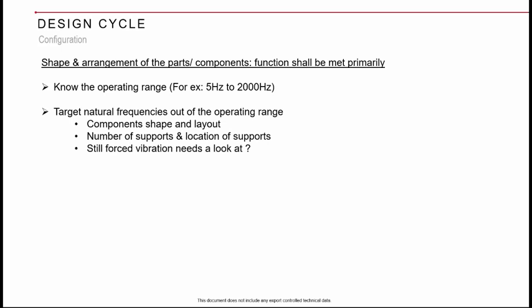See, I have kept my natural frequency away from the operating range, so I don't have any resonance condition now. But still, is it required to consider forced vibration? Yeah, I think yes, sir. Yes, definitely. Even though you have kept the frequency of the system away from the operating range, your system is still undergoing the harmonic excitation forces.